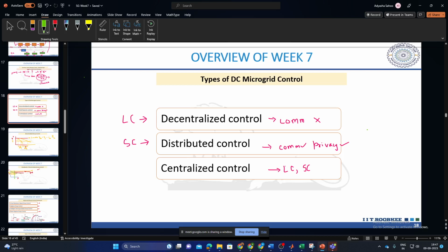I think in the Indian context, only PLCC is working. Sorry sir, which one? In the Indian transmission system, only PLCC is working as communication. PLCC we have, but GPS and all those, I'm not sure whether we are using those modes of communication right now, because smart meters are only now coming up. GPS is only for time synchronization, for PMUs.